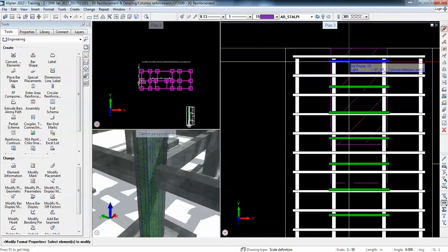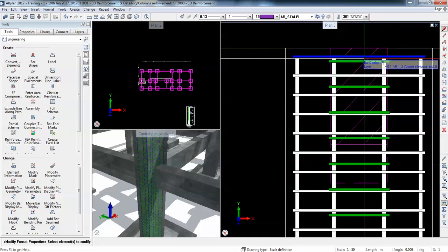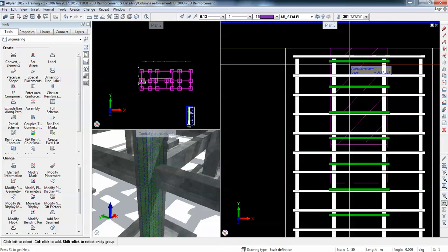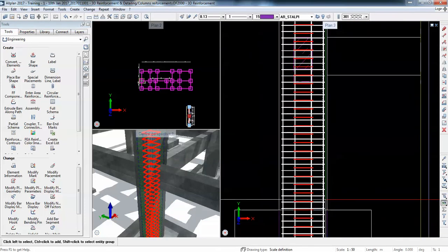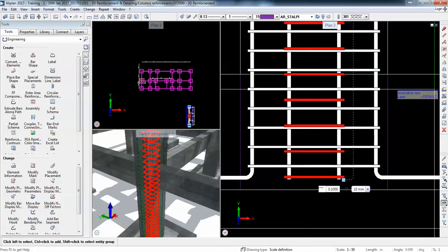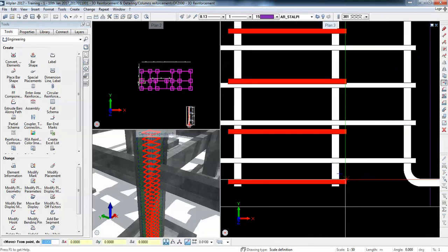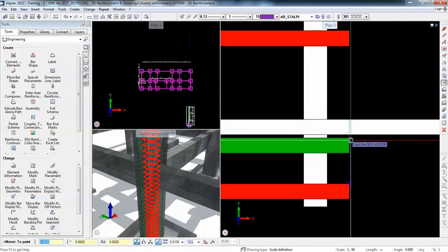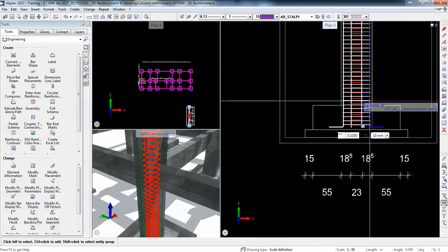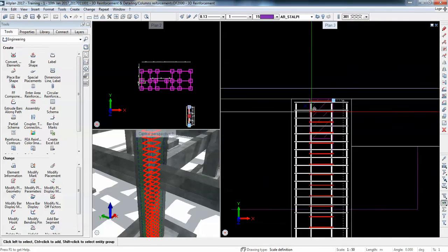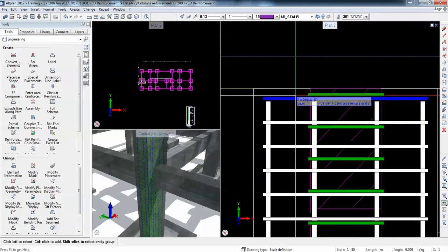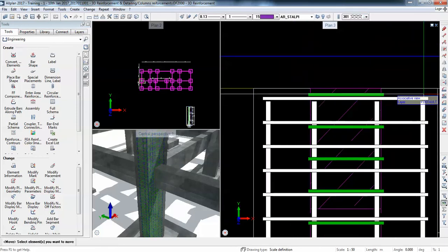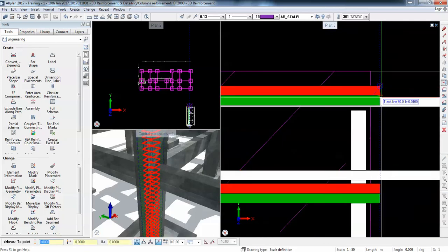just like this. Remember, if you hold the shift button when you click on a rebar that is placed, the entire placement is selected. So I shift click here to select the entire placement, and then I can move these stirrups to be placed somehow under the big stirrup or at a certain distance or in contact. It depends on how I expect the drawing to look. So if I'm not interested in the drawing to have more than one line, I will of course hide them. In reality, they won't be placed like this.